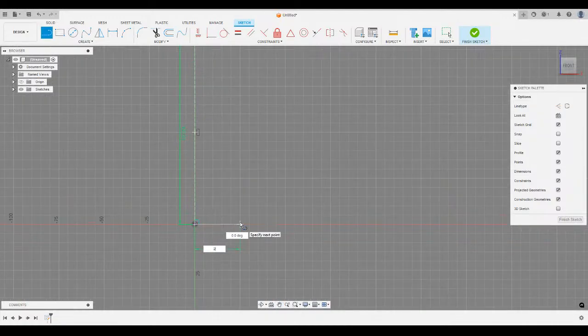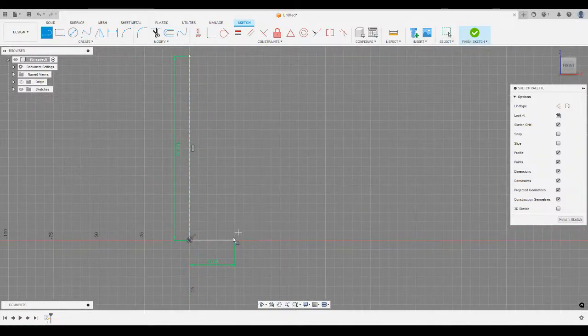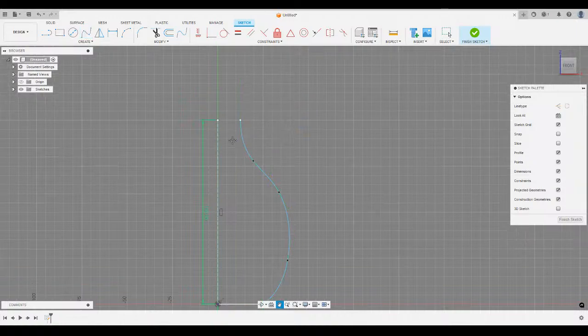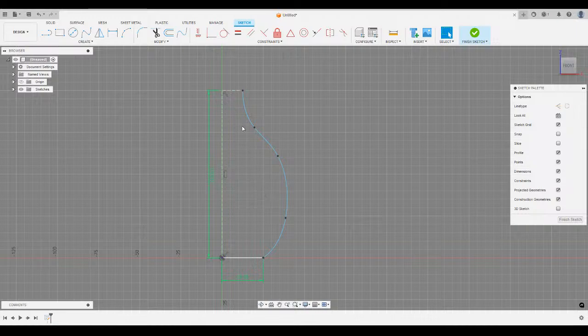Then I'm going to draw the side profile of my lamp, about 25 millimeters. That's probably good. And I'm just going to use a fit point spline to give it an organic lampy shape. Okay, you're making a lamp base right now. Yes. I'm going to draw a line here to here. I want it to be perpendicular. There we go. All right.